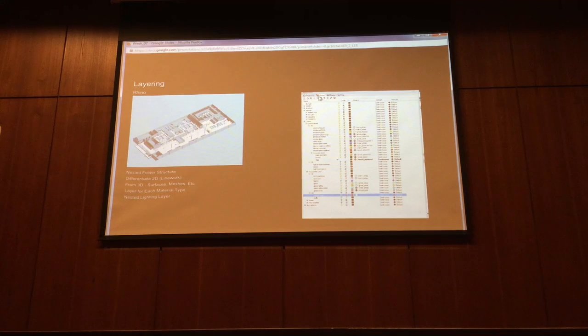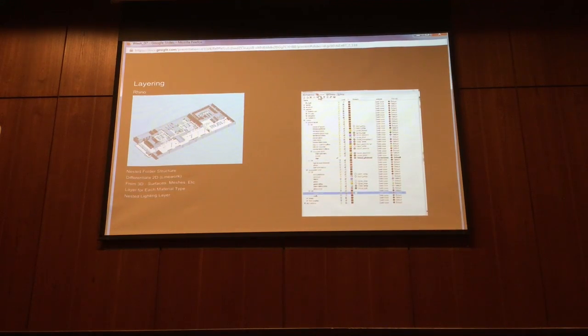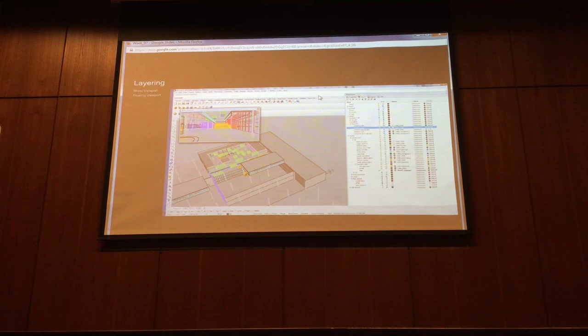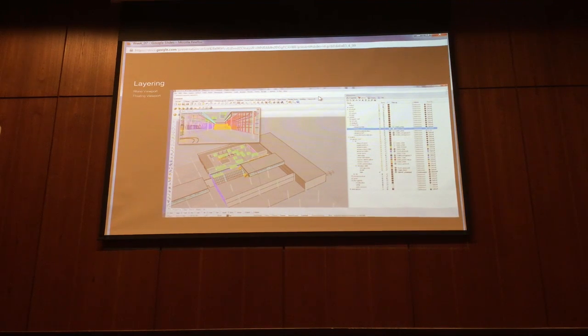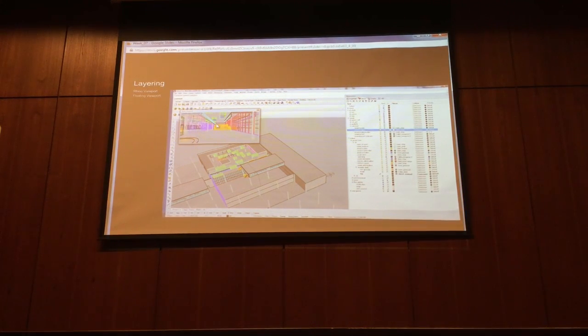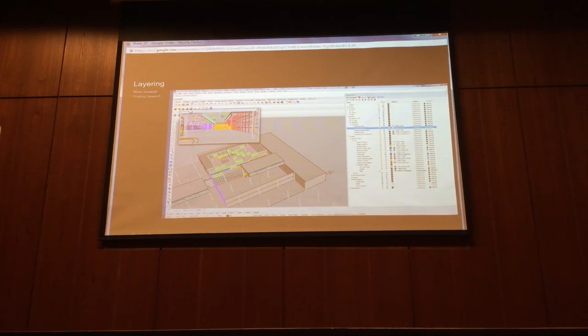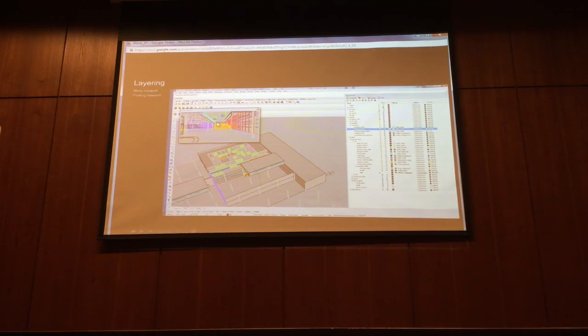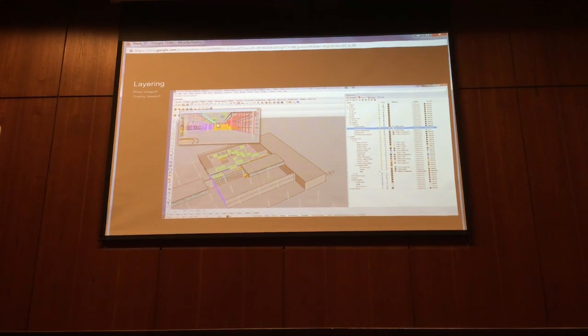Multiple lights in different layers. I have multiple suns depending on my different shots in the scene. A nice command that I think you all should use is view floating viewport. Right? So you can create a viewport that's the same proportion as your final output image to actually know what's going on in the scene. The size of your rendering and your output, it's helpful if you can actually know where you're going to render it. Same thing with that, there's file capture to view. It's a command that saves whatever is in your viewport as a JPEG or a PNG file.